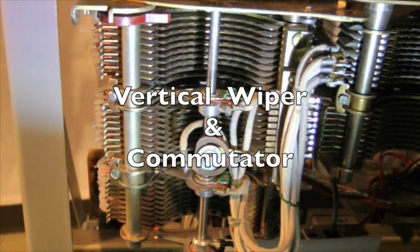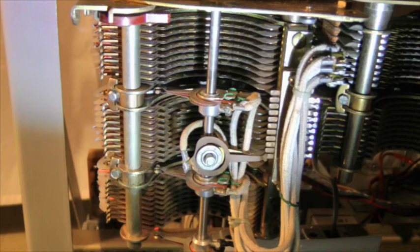Moving further down the shaft to the bank assembly area, we've already talked about the 3 sets of horizontal wipers, but notice that there is an additional single wiper, so mounted that it wipes vertically instead of horizontally. The assembly that has the vertically mounted contacts over which this vertical wiper brushes is called a commutator.